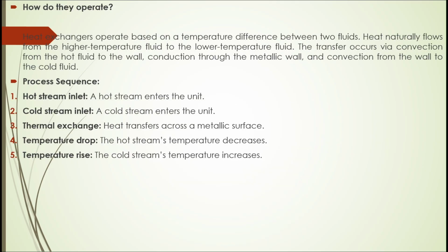How do they operate? Heat exchangers operate because heat naturally flows from a hot fluid to a cold fluid. The heat transfer occurs by convection from the hot fluid to the wall, conduction through the wall, and convection from the wall to the cold fluid.